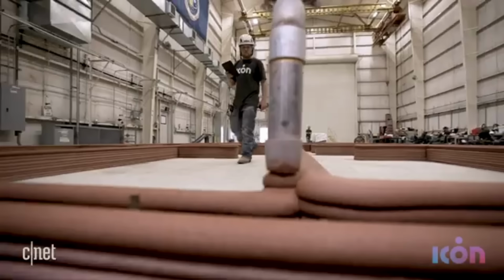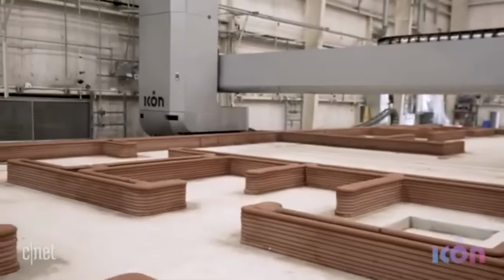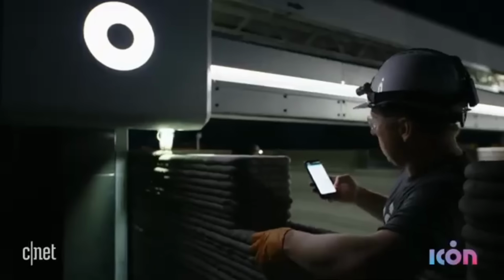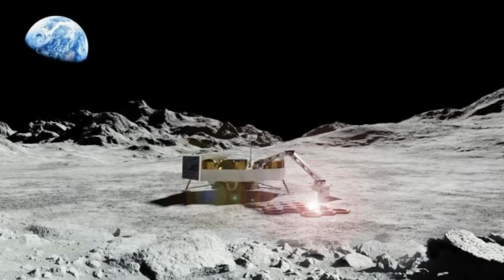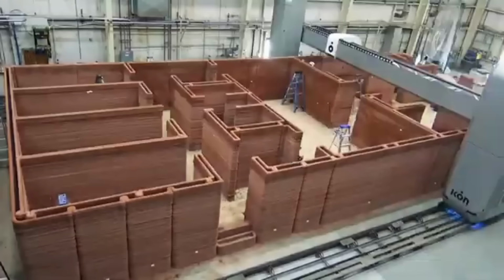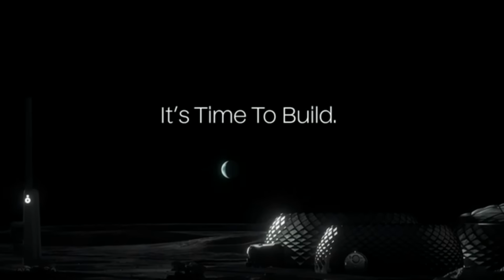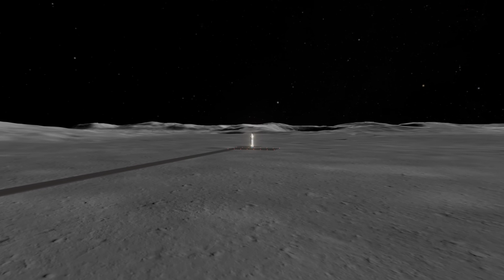The main argument for 3D printing structures is that it requires fewer steps in the process and less energy since it can be done at room temperature. This energy argument really only matters if you are working within some specific mission parameter, which NASA usually is, to be fair. Say your small lunar lander only provides you with 1 kilowatt of power or something. Then you might want to make things using these much lower energy cost alternatives, but it's only lower energy cost once on the moon. But if you want to develop the moon, then we need to count all the energy used in the entire supply chain, which makes importing vulcanizing agents immediately the most expensive approach.